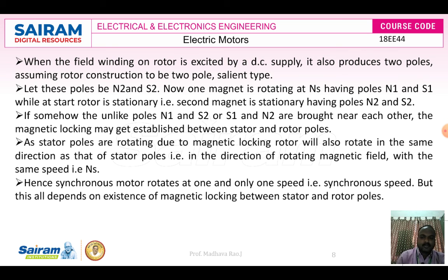The stator poles rotate, and due to magnetic locking, the rotor will also rotate in the same direction as the stator poles, in the direction of the rotating magnetic field with the same speed Ns. This is the magnetic locking principle by which the synchronous motor operates.